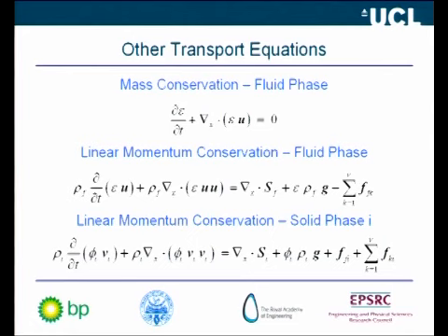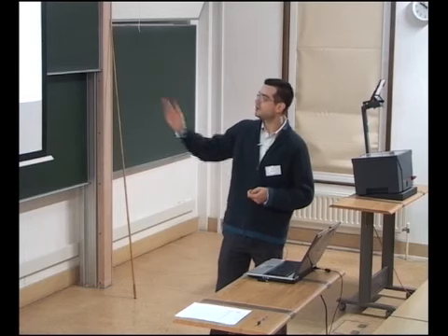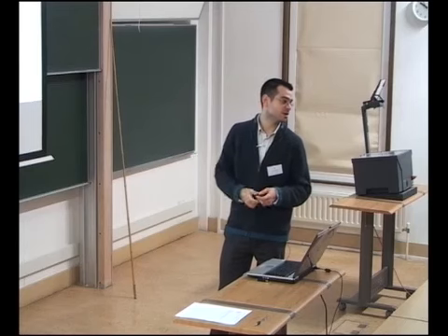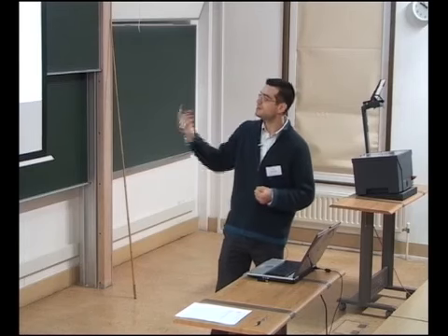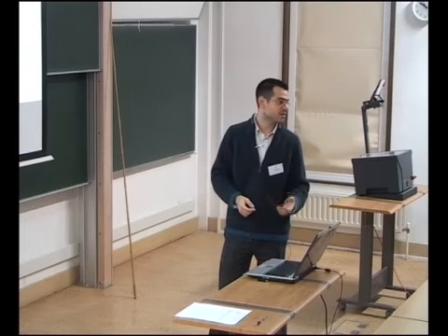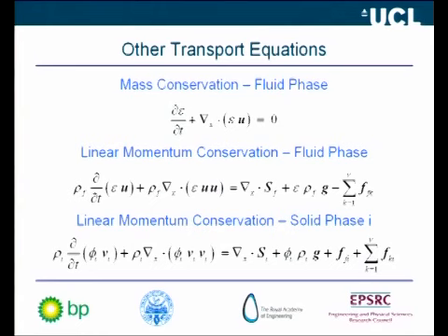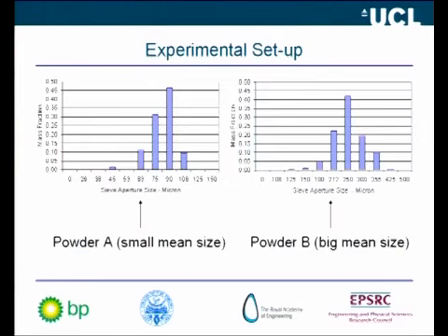So basically the additional equations that we implemented are these: a mass conservation equation for the fluid, a linear momentum conservation for the fluid as well, and finally a linear momentum conservation equation for each solid phase, for each quadrature class. Again, these are not obtained from the population balance equation in this model, but our aim will be also to obtain them by using the quadrature method.